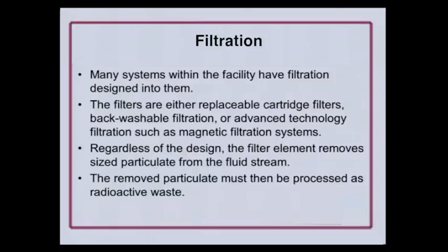As far as filtration, a lot of systems have filters built into them for the purpose of removing undesirable particulates. Well, if it's a filter, it's going to remove that, right? It's going to concentrate it. So then you have that radioactivity being concentrated on the filter. The filter could be either replaceable cartridge type filters, where you take out the expended cartridge, put a clean one in, and then you've got to dispose of this contaminated radioactive filter.